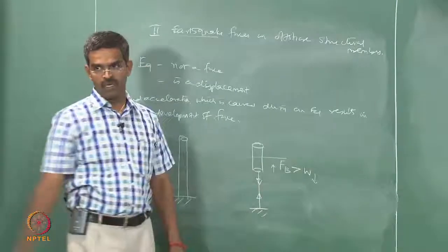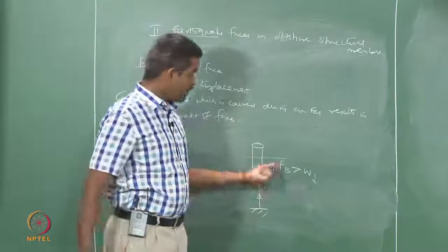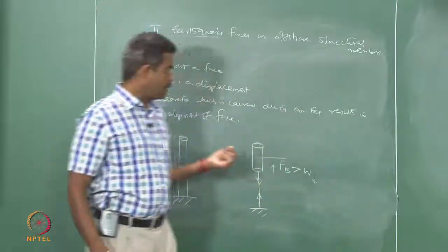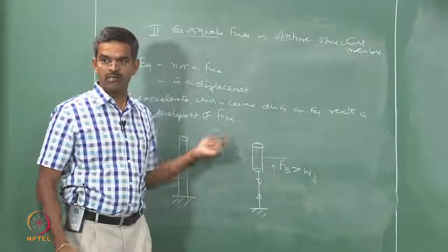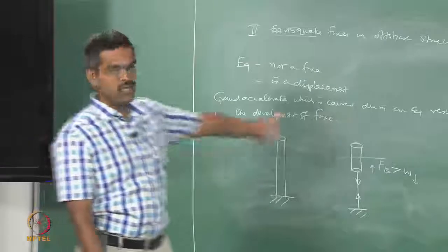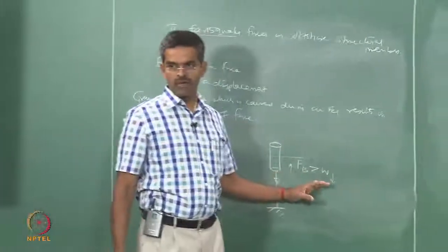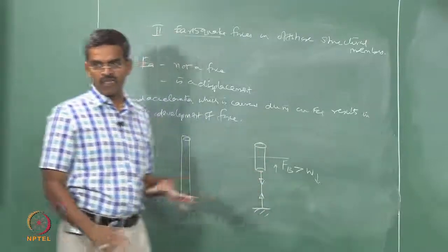That is the design concept. One may ask me a question: why has this design concept evolved, what is the reason? The moment you keep this design concept on, commissioning, installation, towing, transportation, everything is very easy, because weight is compromised on buoyancy force. Simply you float it, you drag it, it will drag. If it would have been the other way, it would have been very difficult to install this. Okay, that is for installation purposes.